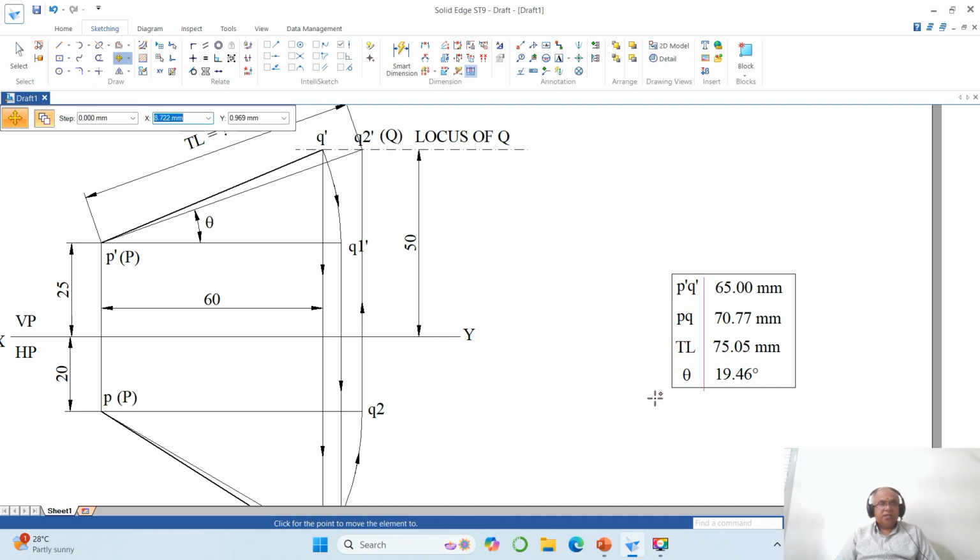So I don't want the displacement in y direction, so you are going to move it in here. Then go to move, select this line, right click, move, select this line, take it here. So I don't want the x displacement, only y displacement is required. You just click on this, and here you click on this.